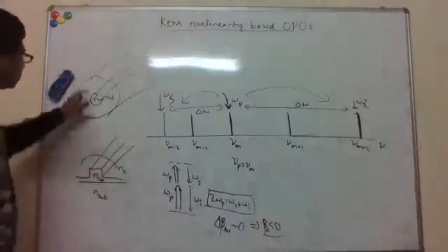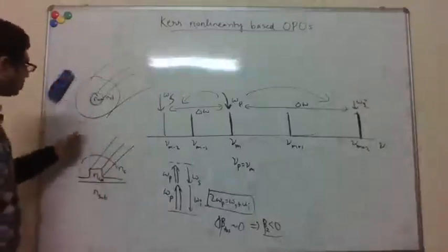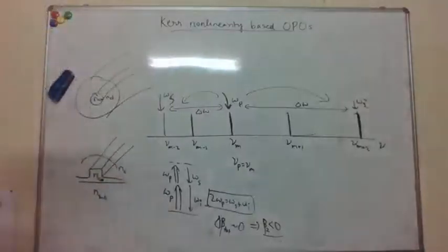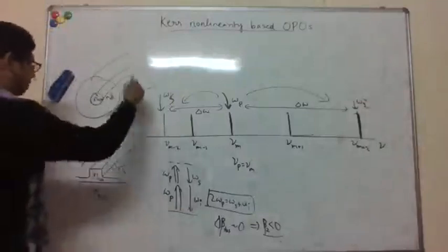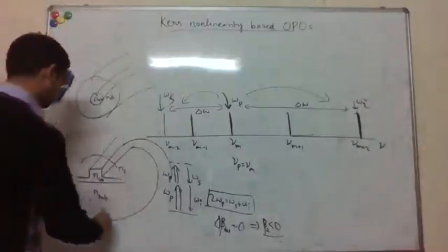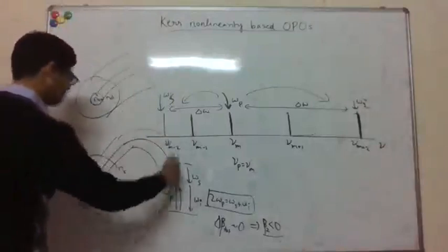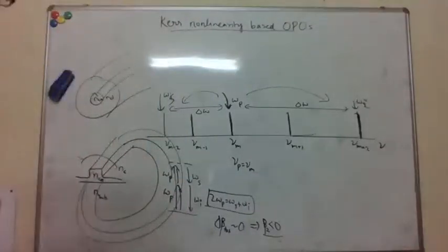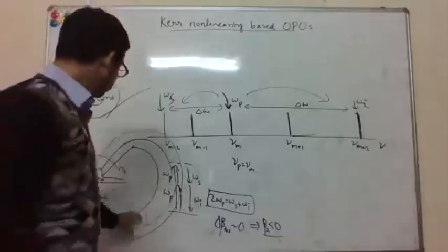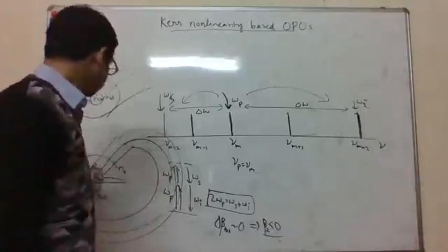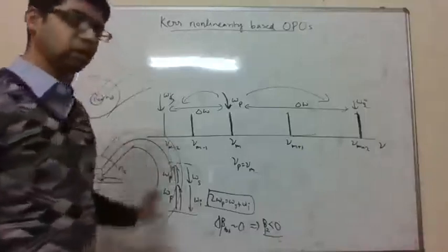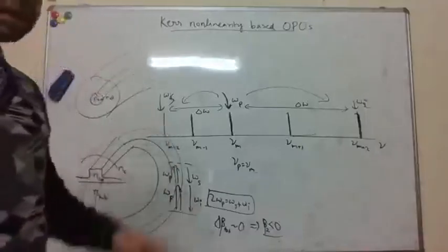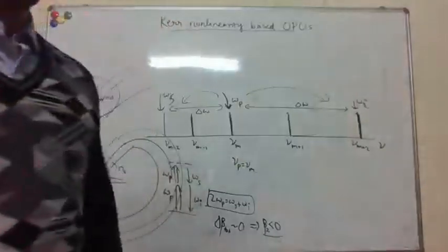The dispersion just depends on the material of the core and cladding, the size of the core and cladding, etc. And now what we are doing is just wrapping it around and making it a ring, right? So the dispersion properties of my ring cavity are still given by the waveguide I started out with, the cross-sectional dimensions. I'm just wrapping the waveguide into a ring.